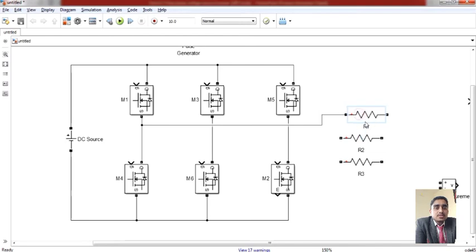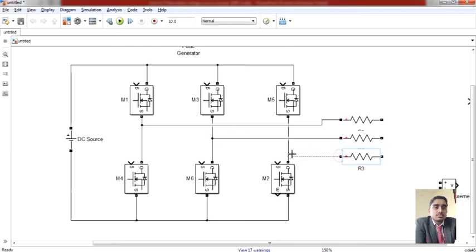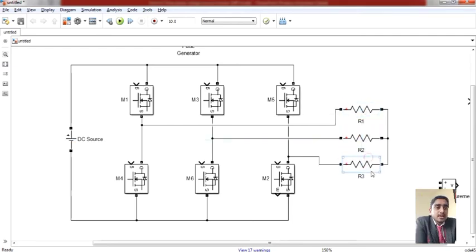So I will change the names and connect PG1, PG2, PG3, PG4, PG5 as required. So I will arrange them in the MOSFETs' order. And I will connect the pulse generators to the gate terminals of the MOSFETs.